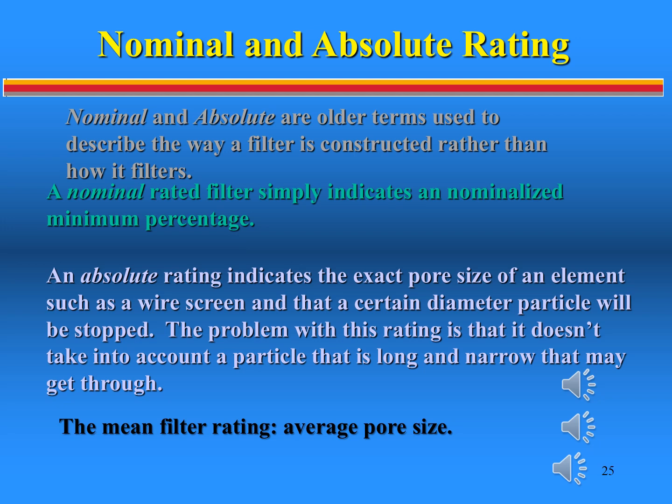It also represents a nominal efficiency figure, or more correctly, a degree of filtration. Process conditions such as operating pressure and concentration of contaminant will have a significant effect on the retention of the filters. Many filter manufacturers use similar tests, but due to the lack of uniformity and the reproducibility of the basic method, the use of nominal ratings has fallen into disfavor.